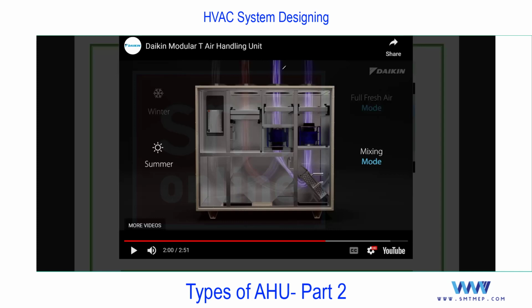You see, this is the return from the room. This is the supply. In the return, some amount, for example say 10%, I'm going to exhaust. And 10% I'm going to add as fresh air, for which we do a calculation. So you see, return air say 90% and 10% fresh. Then again, it is applied to the cooling coil. You know this concept. And again, this is connected to the chiller.